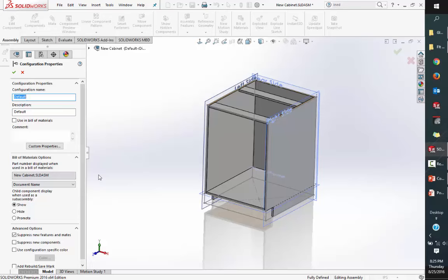And I would say that if you're integrated with a PDM system, a product data management system like Enterprise or even the new Standard PDM, we suggest that you go to the part-for-part approach as opposed to configurations, only because there's a check in, check out process in the background that has to happen. So it's easier to take a new part and check it in. It comes down to: do I want to deal with a part with hundreds of configurations or with 100 parts? We find that dealing with 100 fasteners inside of a PDM system with search capability and all that good stuff ends up being a little nicer. So it does use configurations, but it does have options not to.